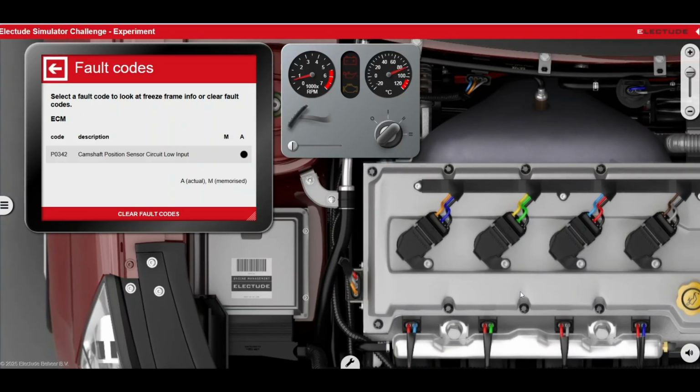Yeah, the coolant temperature has reached. I hope you had the fan come on and then off again a moment ago, because the engine warmed up to the limit and then the fan kicked in and then the engine cooled again and then the fan went off. That's normal operation. It would happen especially if you are in slow moving traffic.